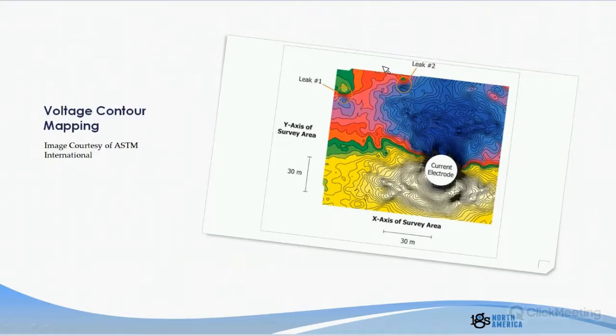So what we're looking for in a leak is the exact opposite pattern as the current electrode. See, current enters the pad via the current injector, and it exits the pad via the leaks. And so they end up looking like the opposite of the current electrode. So the current injector has positive on the bottom, negative on the top. The leaks have positive on the top, negative on the bottom.